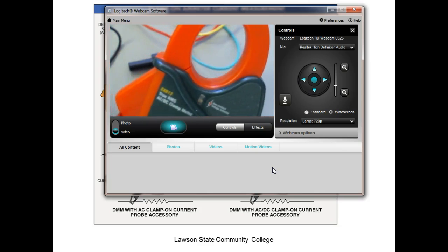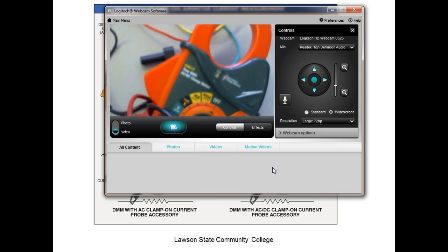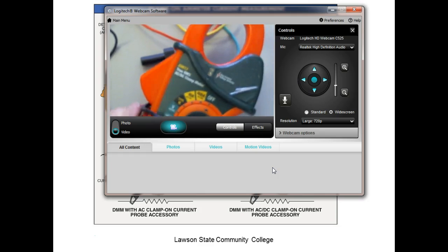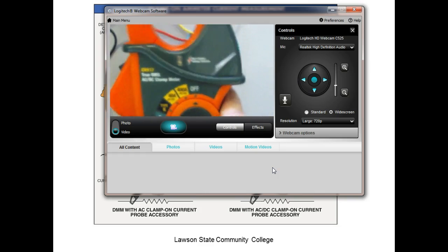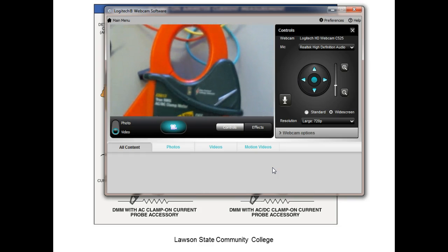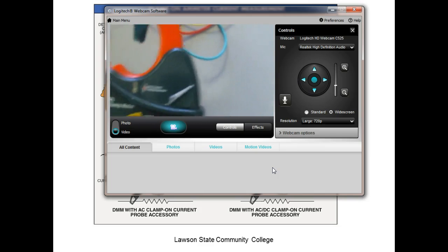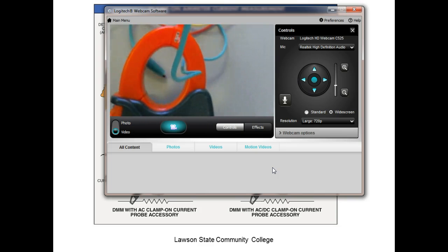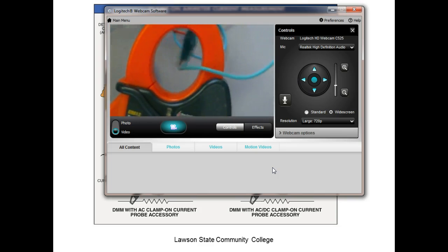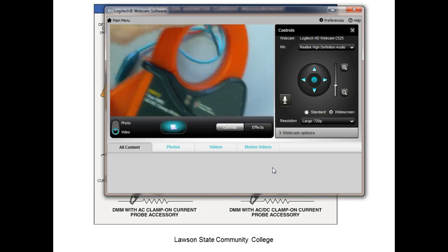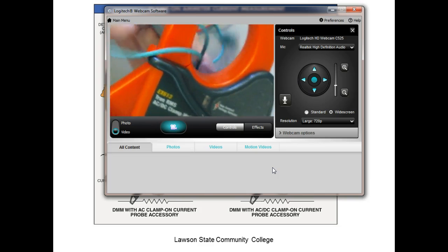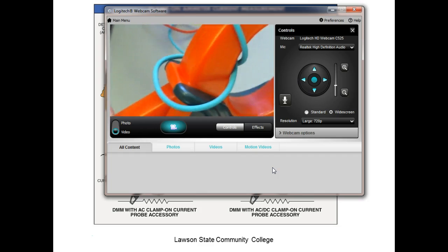Explain that a little bit more. So what we would do is, normally we would come in here and measure it like this, right? So we'd take our clamp-on meter, we'd open it up, we'd put it across the wire, and we'd measure this. Well, if I come over here and did this, just run it through again, if I got enough slack, now my meter would measure twice what's there.